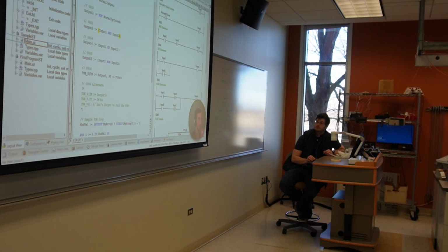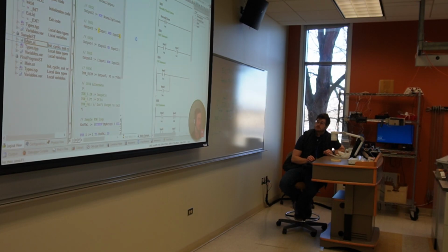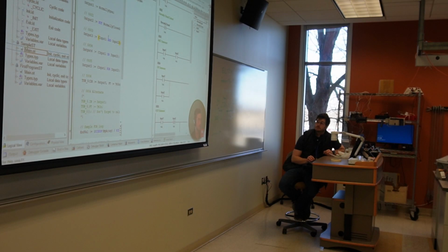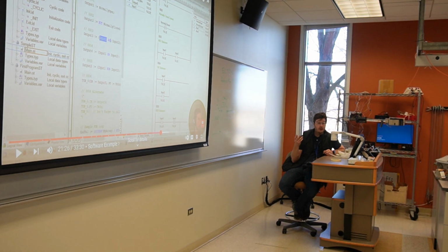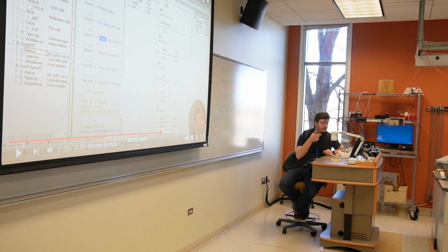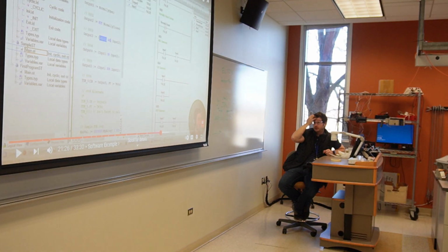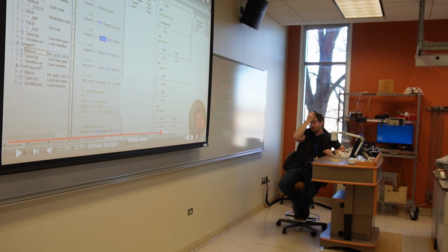It may make sense to hop in here and show a quick example of that using our watch window. Let's drag output 3, and we'll drag input 1. What he's doing here, and we actually have access to this too, is using a watch window. If you go up into your toolbar, into the Windows list, root around in there, there is a watch list or a watch window.